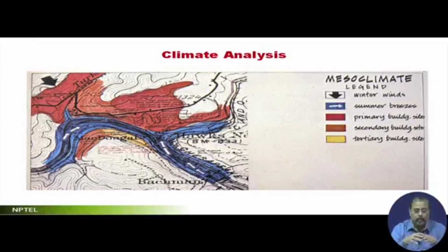projects as well, that you are trying to find out with respect to the site how the sun is radiating its rays to this particular site, which portions are the shadow zones, which portions are the lighted zone or sunshine zones. In terms of wind, what is the wind direction, what is the frequency of wind flow. So wind velocity, the variations of the wind velocity, which is represented in terms of wind rose diagrams, that you are going to check.